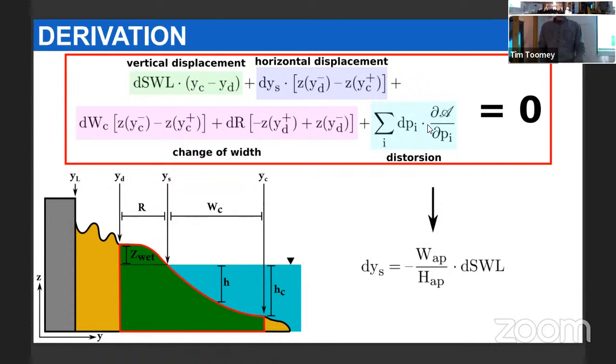Yes. And so the particle size is a parameter in the model. Yes, it is a parameter, but there's no other material parameter like the shape. It depends on which formulation you consider. For example, for critical bed mobilization, I think it only depends on the sediment part, not on the wave part.